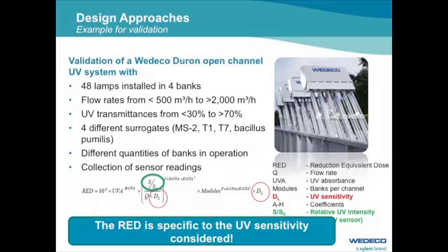And in order to allow later on a safe operation in line with the disinfection results, we are collecting sensor readings. There is a sensor in each of the banks in order to monitor the level of intensity which is delivered by the system. And that is later on the parameter which is used to control the system in a way that it's always delivering the performance required.